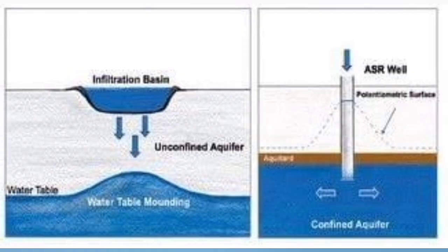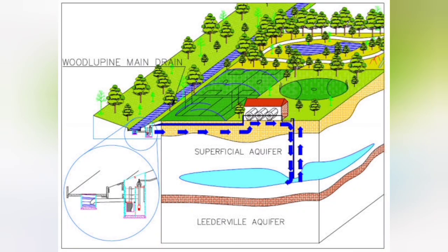Whether there is any gap in the data of subsurface geology, whether the available lithologs of any boreholes in the area are sufficient to arrive at a correct picture of aquifer geometry of the area. Whether the available data on the aquifer parameters is sufficient in case the area shows promise for artificial recharge techniques for deeper aquifers through injection wells, etc. Can the available groundwater structure serve the purpose of monitoring the effect of the artificial recharge project?